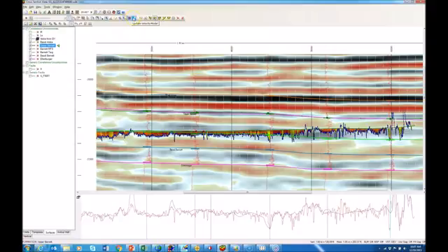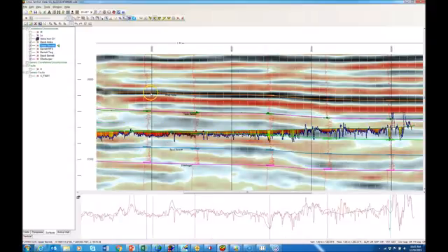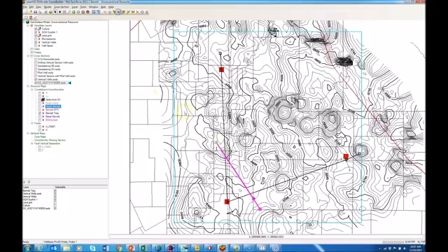So let's go ahead and update the velocity model. We'll take those depth points, combine them with the back interpolated time value on that surface, and update my velocity model. So now I've got the most up-to-date geomodel and up-to-date velocity model possible. So if I were to then decide to plan a well, say in this area, it will be planned into the most up-to-date geomodel possible.